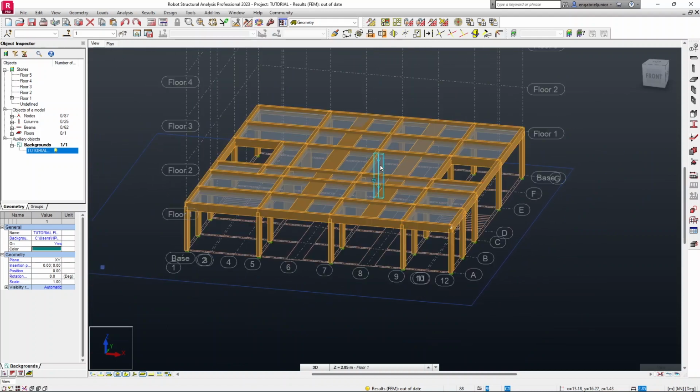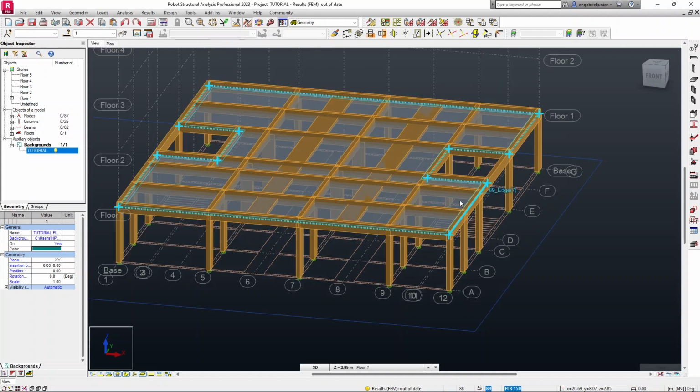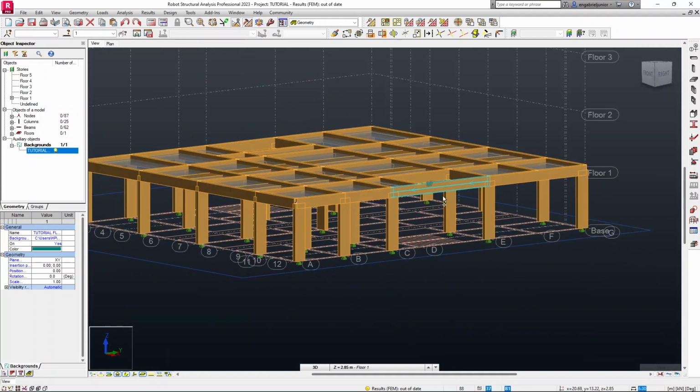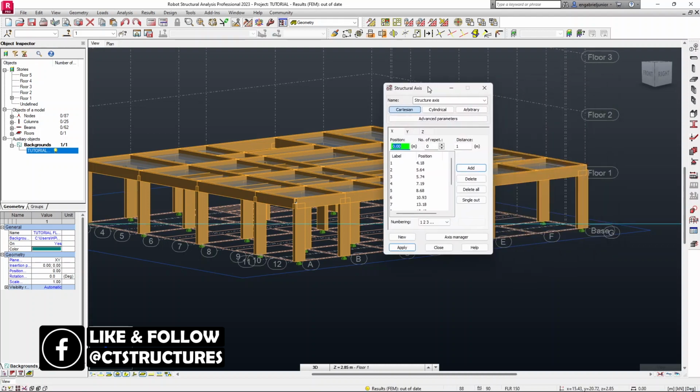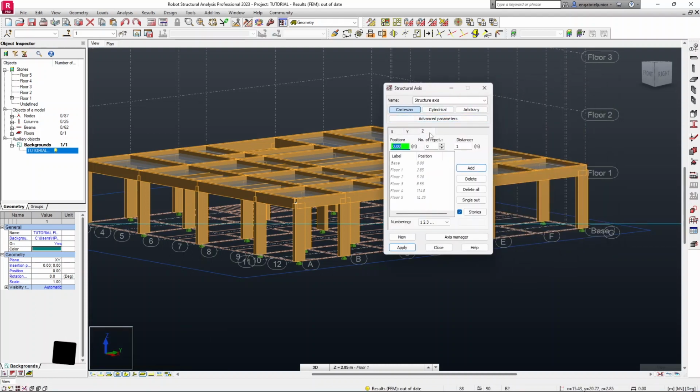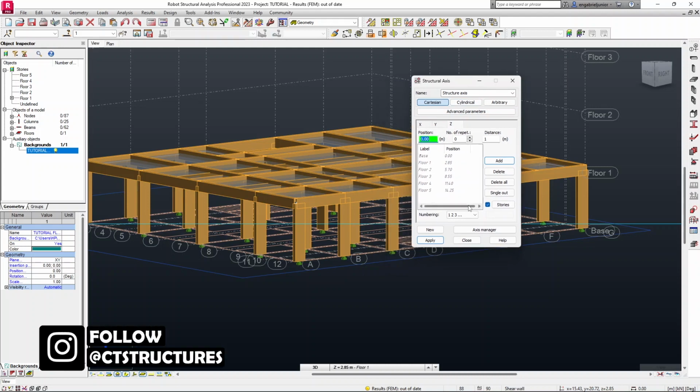The next step, I want to draw the staircase, and this one is a bit tricky, but we'll have to do it. So beginning, we go to just the axis definition. I want to start by first creating a level where the landing will be. So the story height is 2.85, so I'm just going to pick half of it. Don't think I can remember it offhand. Let me just calculate it. 1.425. So I'm going to pick a distance of 1.425.